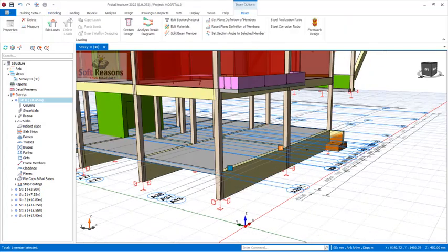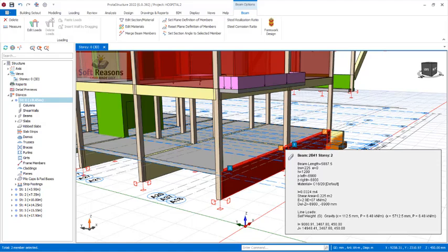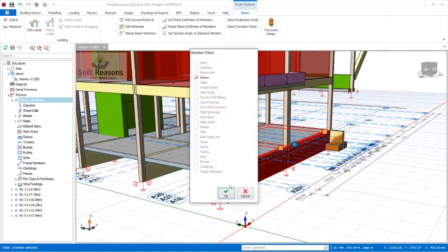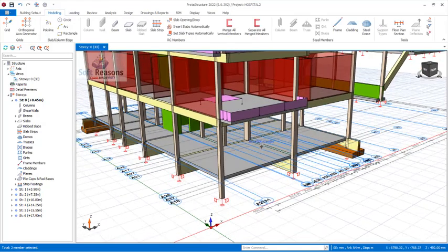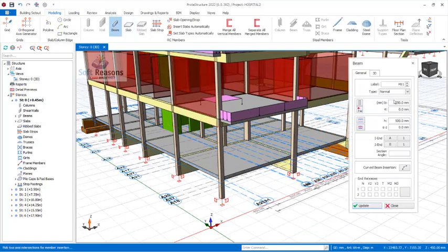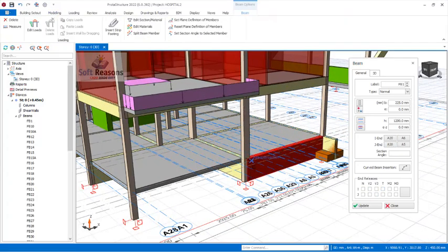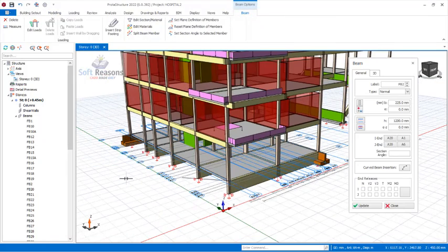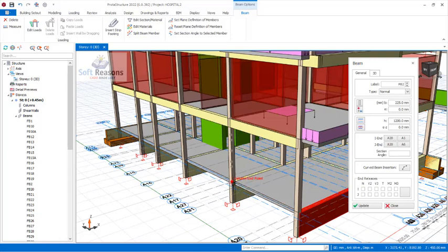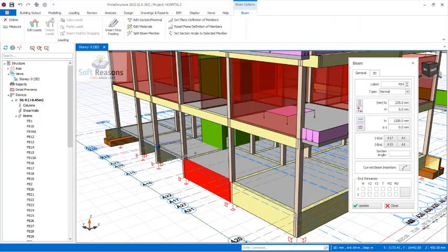So we have to insert this again, so we wouldn't have some errors during analysis. Having deleted all of that, we can click on the beam right there. Now the program is seeing it as a foundation beam, so 225 right there, and this is going to be 1200 millimeters, after which you can pick this from this point, connect it to this column, so you can see it having it inserted successfully without popping up any message or any warning. So I have that inserted just like this.